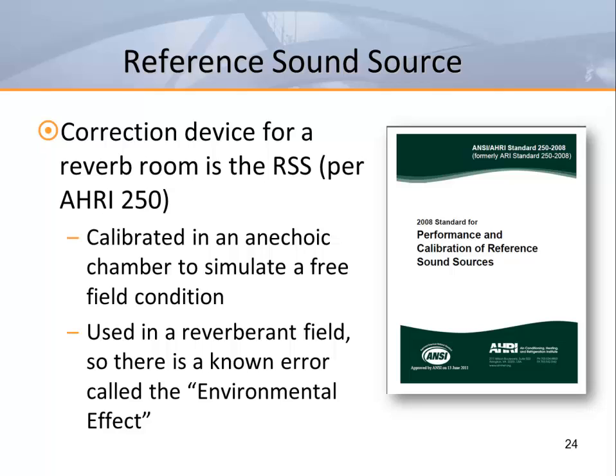AHRI Standard 250 defines the reference sound source, or RSS. This device is calibrated in an anechoic chamber to simulate a free field environment, but for our purposes is tested in a reverberant chamber. It therefore has a known error called the environmental effect that must be corrected in our calculations.